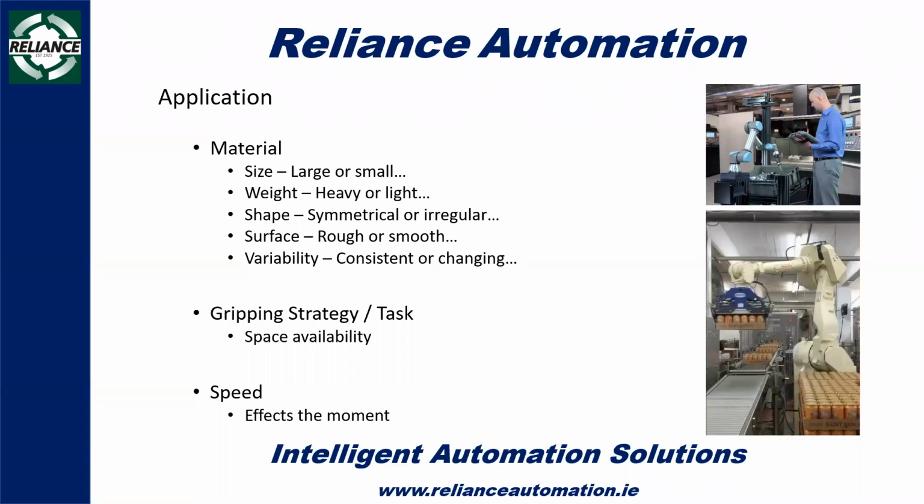So to go into them in a little bit more detail. The application is probably one of the most important pieces. What we're looking at is the piece that you're actually looking to pick up or to interface with, and the sizing of that piece. Obviously, if it's quite a small piece, it's going to need a smaller end effector. And similarly, a larger piece is going to need something with a much larger stroke on it.